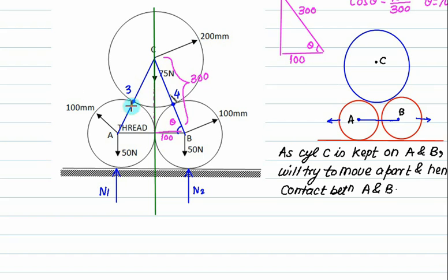the mirror image of this part. Exact mirror image. And even the load on this side, is it same as the load on this side? In mechanics, this type of loading is called symmetrical loading. You don't have to solve everything. If you solve this side, automatically the same answer will repeat on this side. That is the advantage of symmetrical loading.